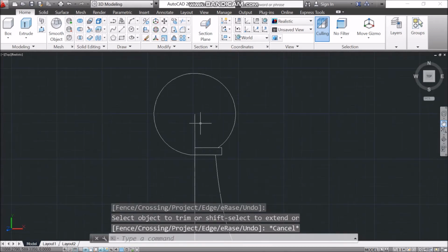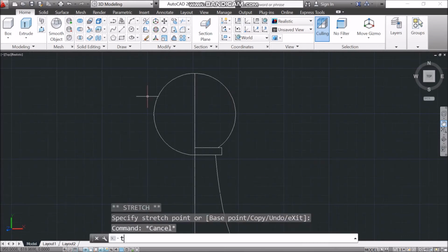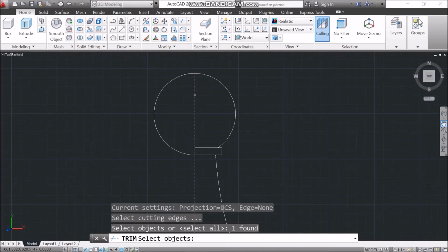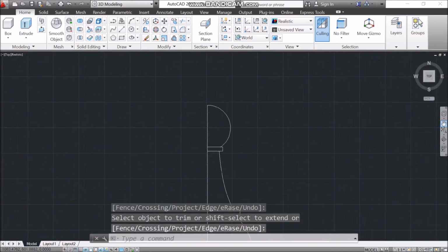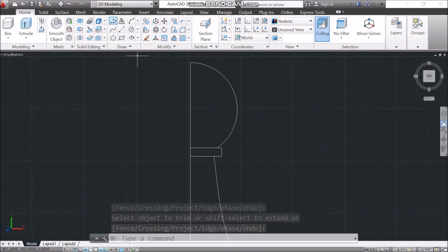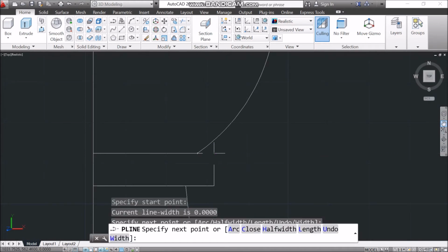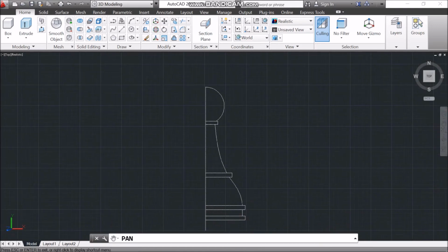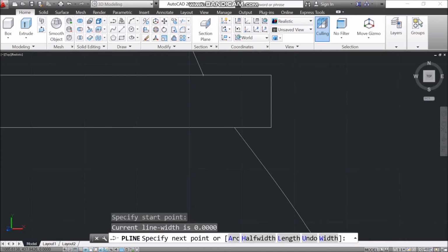This and then put this in the end of the circle, then trim again. Click on the first line that you wanted to be the path or the section which would be the guide for us to trim a certain element in here. Okay, so once done, all you need to do is trace all of the edges using P line again. Just the edges. This one, this one, this one, this one. Enter. And then same with here. Using P line, trace the edges.